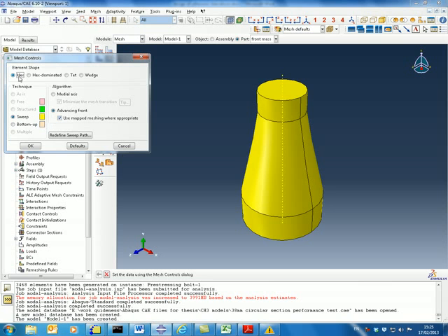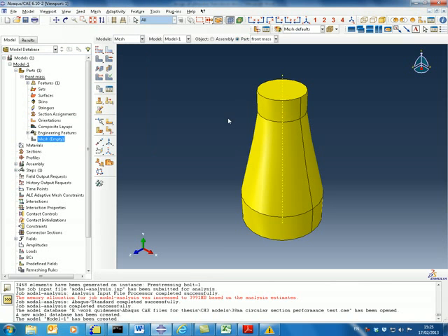The preferred one for modal analysis is hexagonal and structured. So in order to get any of these techniques, you have to divide your geometry into different sections by using partitioning. Partitioning just creates a plane between the mesh. It does not separate the model into parts.